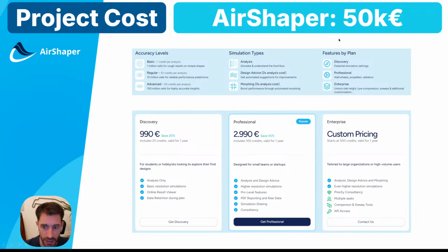In terms of 3D modeling, the support that we got via Voyager, let's add another 50,000 euros. For 100,000 euros in total, we took this car from a drag coefficient of 0.311 all the way down to 0.22. And of course, it really depends on how much design freedom you still have. But if you let us do our thing as a standalone team, we can really come back with the wildest improvements. And the sooner you involve us, the more room there still is to optimize the design.